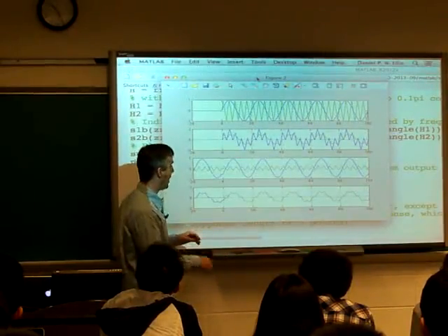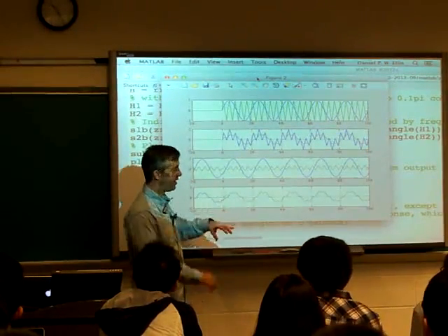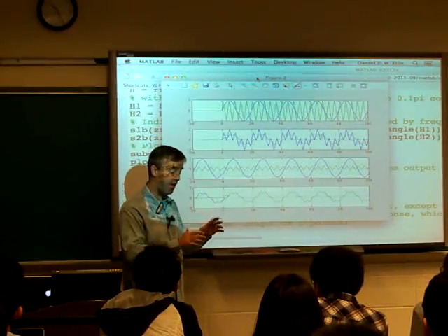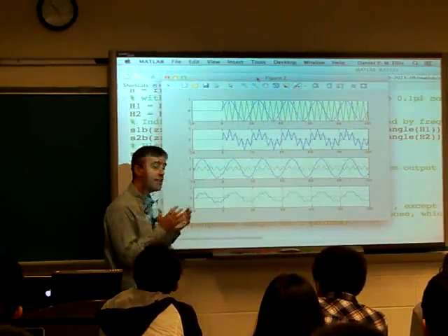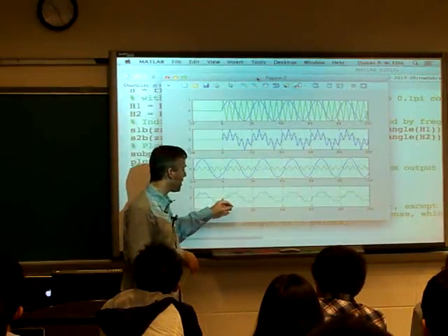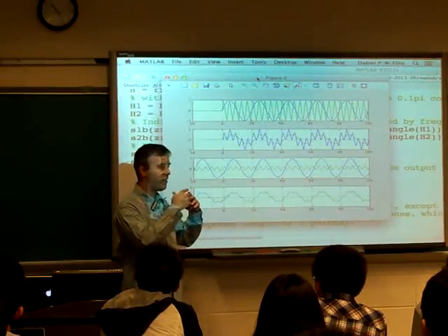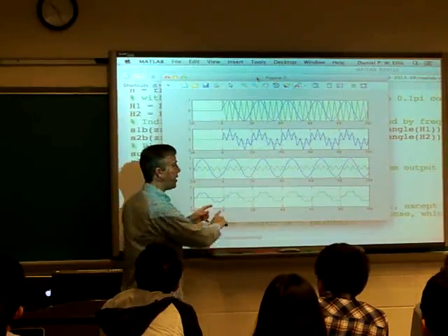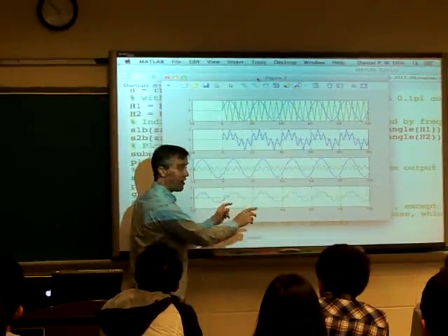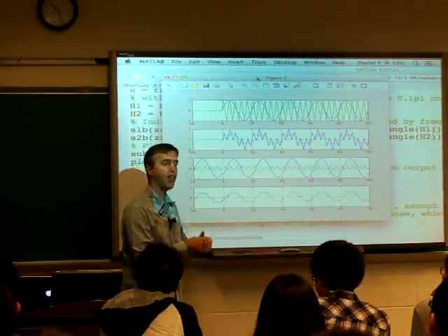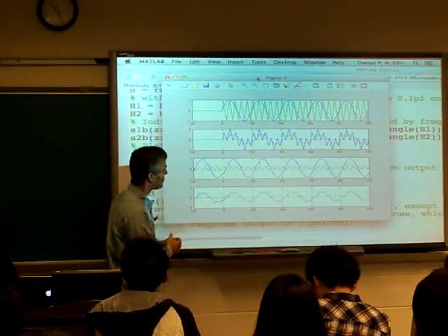That's the fact that, yes, they're not going to be the same because there's some region where the sinusoids turn on where they're different. But because the impulse response here is only 5 points long, and we said the transient difference was dictated by the tail of the impulse response after n points, once we've gone more than 5 points in, they're actually identical, right? Because the transient response has finite duration in this case.